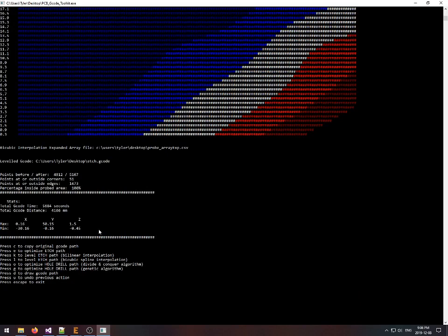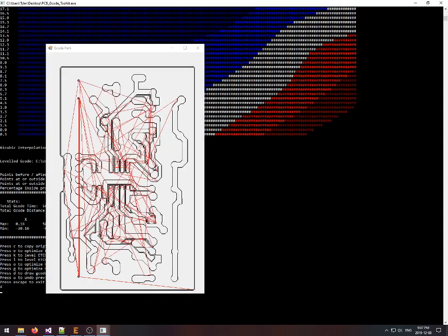Now, the other thing you can do sometimes is cut two boards on one PCB. If I look at this Gcode, I'm just going to hit D for draw. Now, it's fairly small compared to the standard. I usually carry 5 centimeter by 7 centimeter PCB blanks, and I can fit a few of these onto one board. So what I'm actually going to do is create 2 copies in one Gcode so that I can go ahead and cut 2 boards in one go.